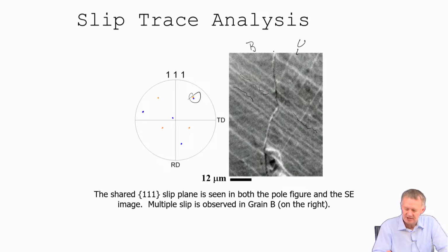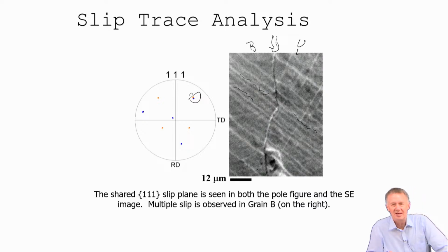The other thing you'll see, this isn't a nice straight boundary, right? If you look at that boundary, you can see the jog in it. And the reason is the incoherent twin is not a nice stable boundary like the coherent twin boundary, which would be a nice plane that we are looking at. So it's not stable. So this was a diffusion bonded crystal. We did diffusion bonding to make that type of boundary that we wanted to look at. And that's what we got, right? So we can make the boundary, we can force it to have that boundary, but it doesn't want to be there.